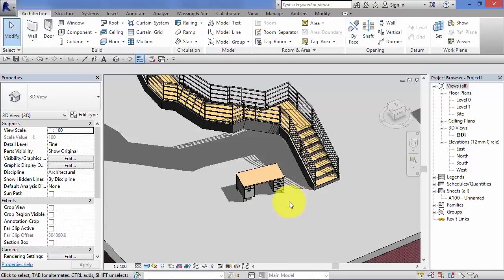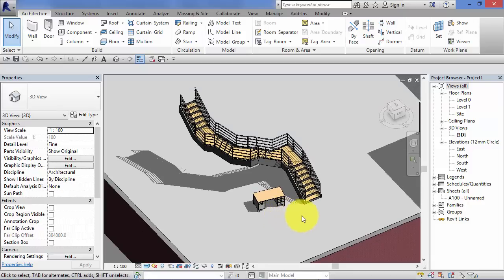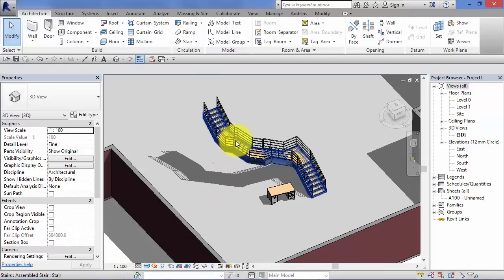Revit families or component families have a .rfa file extension, which stands for Revit family, and those are fundamentally different from the system families, which only exist inside each specific project that you create them in. So as I said, walls and stairs, also roofs, ceilings, floors are all examples of system families within Revit.